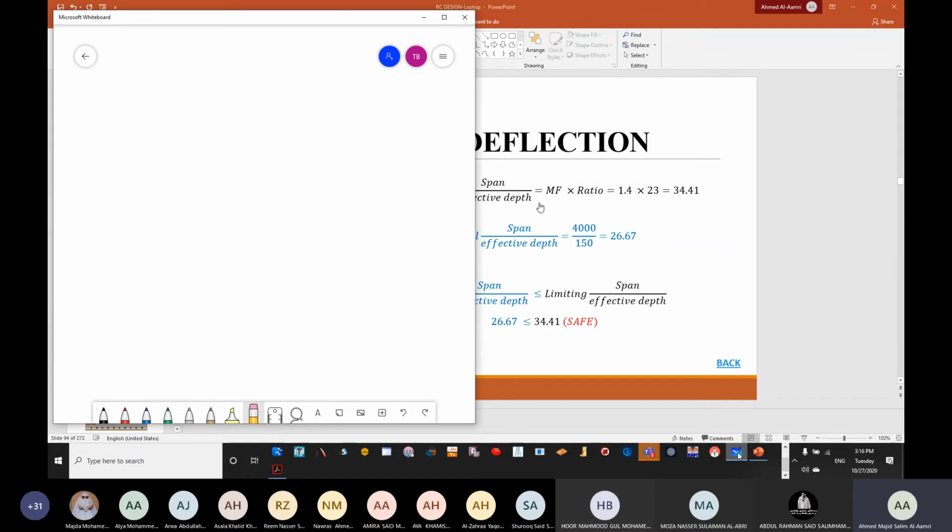Okay, once again, we'll return. See here, we have an equation. You have studied that deflection is equal to moment divided by EI. Have you studied this equation? Very good. So whenever the moment is increasing, the deflection is increasing. So for me, the most critical situation is wherever I'm going to check for the highest moment. The highest moment was for X. That's why I need to use the dx. Is it clear now?